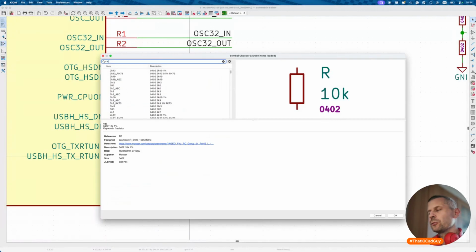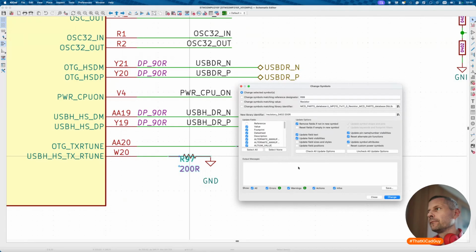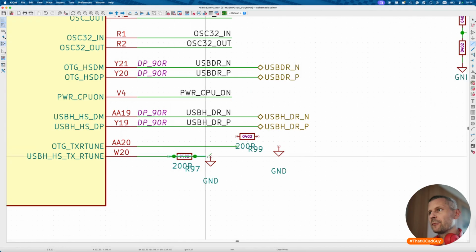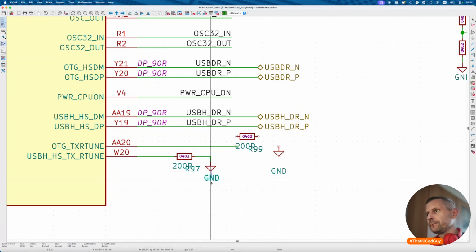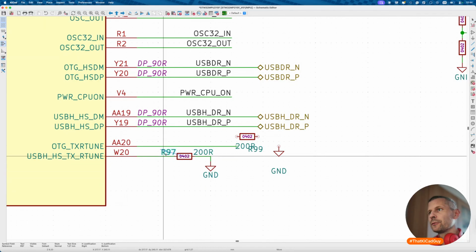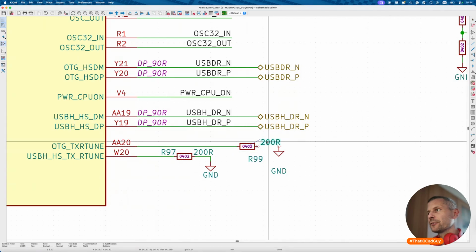And when these two resistors can be in 0402, then I believe the resistor for the CSI-RX can be of this size as well, because it's the same package, the same issue, the same size constraints.